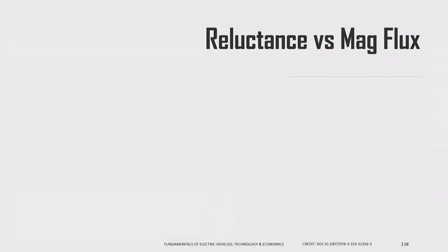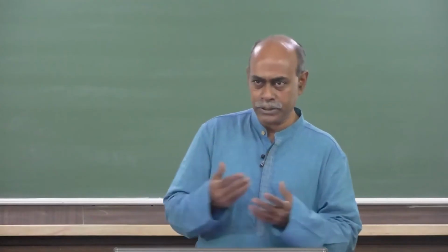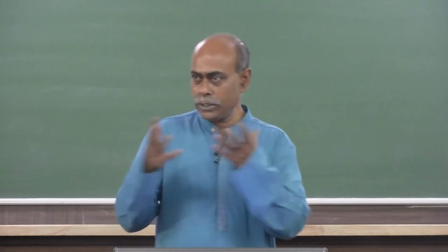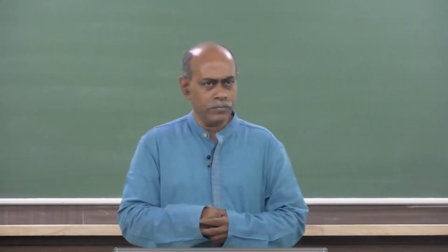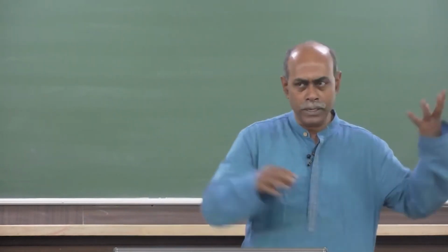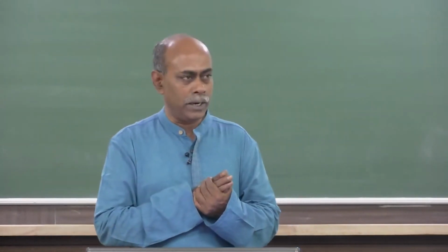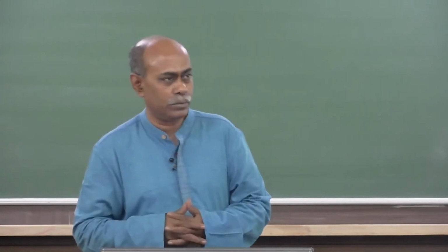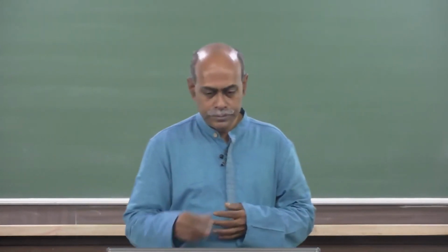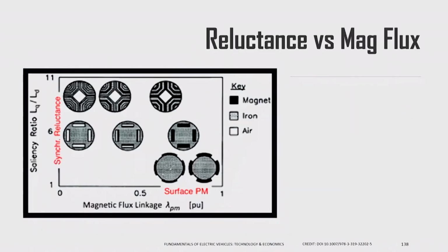So, what people have been wondering is, we already seen that PMSM motor has magnetic torque and reluctance torque. Can we increase the reluctance torque part and reduce the magnetic torque part so that we do not depend upon strong magnets? And this is possible. There is what is called a continuum, there is a range of designs possible.